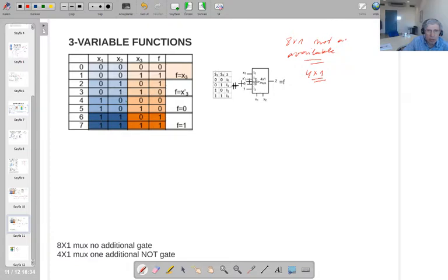So you've got this mux. This is the function table of this mux. What it says is, when these variables, the select inputs, are 0, 0, then the information is transferred like that. That's the definition of it. You might also call it the function table. So it is possible to answer that question. You can design the 3 variable function by using a smaller size mux. How are we going to use it?